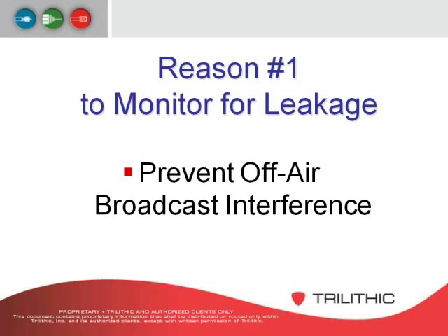So let's say you have a VHF channel at channel 4, but you also have a cable channel at channel 4. If you have ingress coming into the cable, then it will try to take over that cable station, and you'll see the two channels trying to run together, which usually shows up as some horizontal lines on the screen. And that's all from off-air broadcast interference.